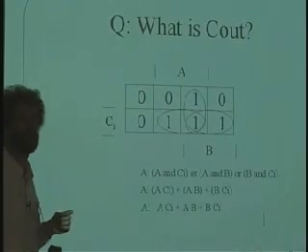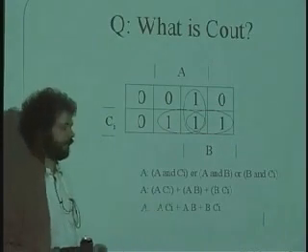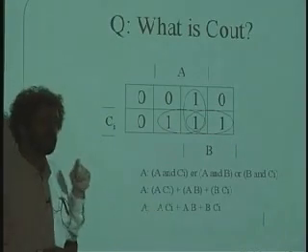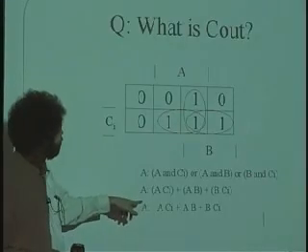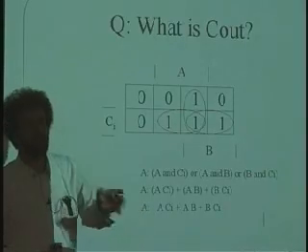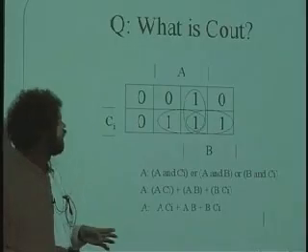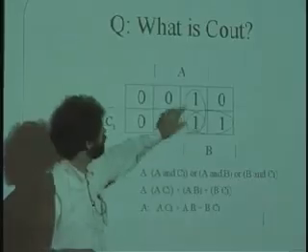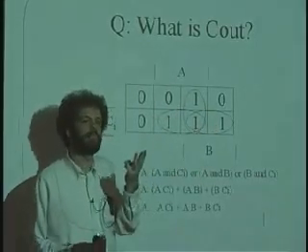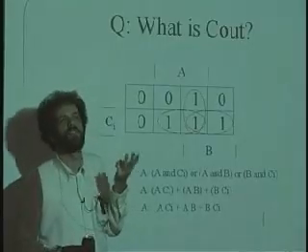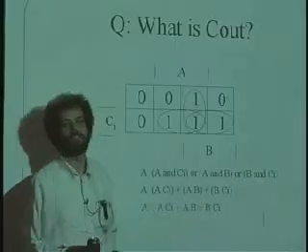Now, you could do it, okay, but it would take a lot to finally see the symmetry in all of this stuff. And if you think about it a little bit more, what is the logic here actually saying? At least two of these have to be 1. You got it. That 2 or more of the inputs need to be 1. And this tests for these 2 inputs, this tests for the other 2 inputs, and this tests for the other 2 inputs. You have 3 wires. There's 3 ways to test for 2 of them being 1. And so you just OR up those 3 cases.